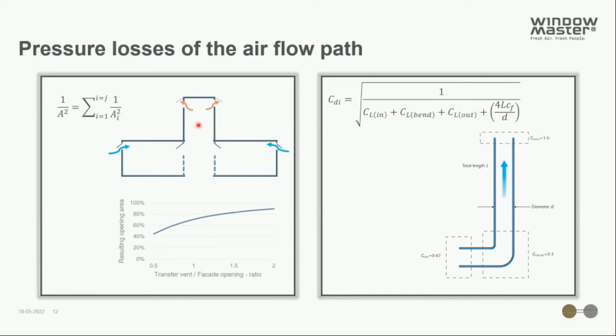Now, if these pressure losses become too complex, if you have too many features, we might need to utilize more advanced tools in order to estimate these correctly. Or you can, in worst case scenario, calculate the zones as just single-sided and see the thermal buoyancy or the stack ventilation to the clerestory as a bonus.